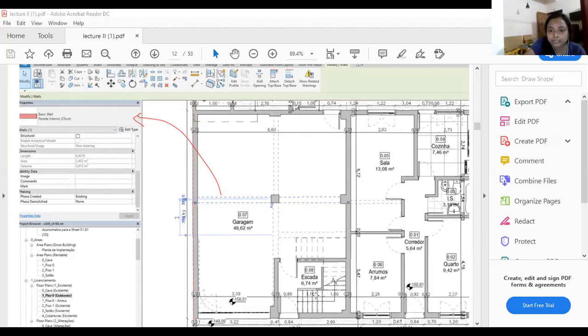At the same time, in the staircase also, we use this kind of more elongated dashed lines to represent the staircase which is above. These are solid lines which is representing the staircase below. This is the dotted line which is representing the staircase above. So in any kind of professional practice, it is very important that we know how to present our drawings, because presentation of drawings matters a lot, and this is the key which makes a variation to become a good designer or a bad designer. Fine.